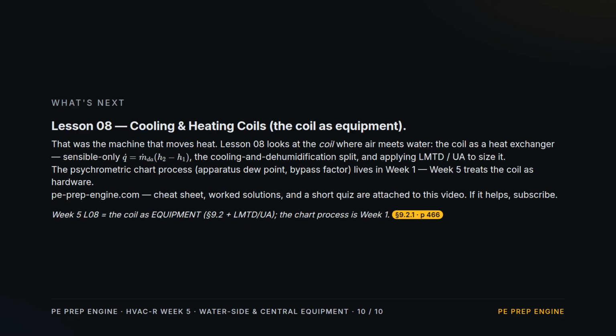Next, Lesson 8, Cooling and Heating Coils. The coil treated as equipment, a heat exchanger where air meets water, with the sensible and latent split and LMTD sizing. The psychrometric chart side, apparatus dew point and bypass factor, is back in Week 1.